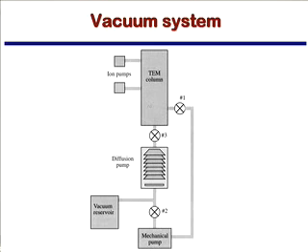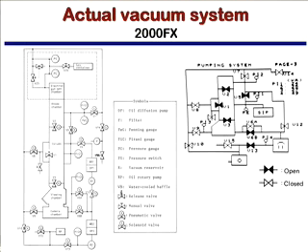So it's a multiple part process where you use one pump to go in one range of vacuum, the low vacuum. You need to get down into the medium vacuum, and then preferably towards the high vacuum regime with either the diffusion pumps or the ion pumps doing that work because they're vibration free. Every microscope has a different vacuum system, and when you start to use a microscope, you need to go through and look at the diagram that's associated with that microscope. Usually the thing on the left comes from the manual, the thing on the right comes from the little screen that we have as our interactive gauge with the microscope as we use it.